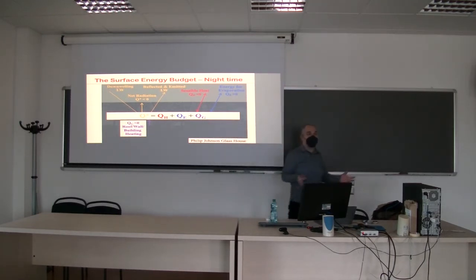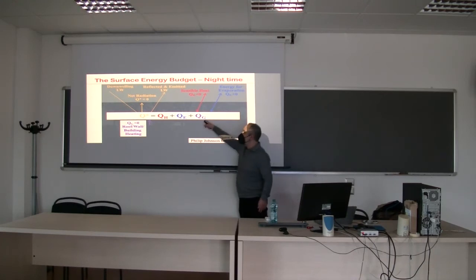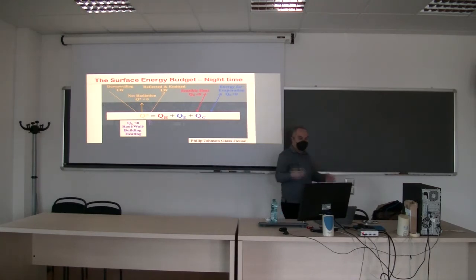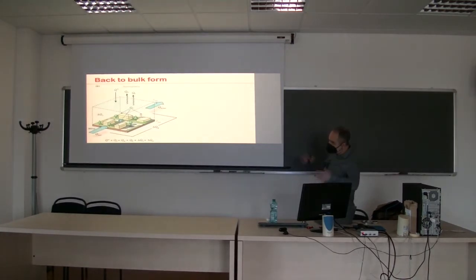Now, you would notice that this storage that became a source of energy in the evening is very important when you think about the city. The nighttime urban heat island is mainly driven by all the storage heat QG that at night starts leaving the ground. So this is for the smallest or thinnest element of the city, just a little interface, let's say, between the buildings and the atmosphere. Now you can think at a much, much larger scale.